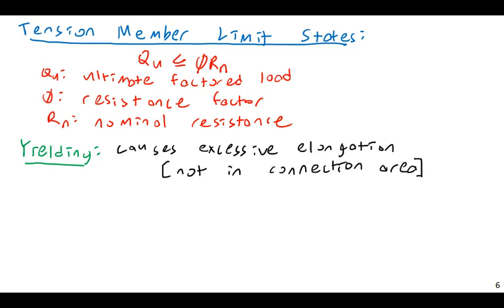That causes cracking in drywall, siding, and brickwork. Brick, glass, and drywall are fairly brittle materials, so if you have excess deformation, even if the structure itself is standing, you might have damage to your non-structural elements. So yielding is often itself a limit state.